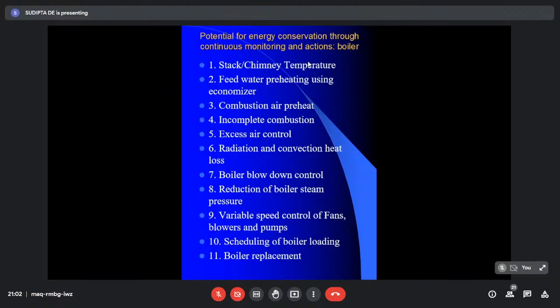air supply side. You have some measured parameters or monitoring factors, and the fuel ratio is also controlled accordingly in the system itself, but still it is increasing, which means there is some incomplete combustion and you have to increase the excess air.